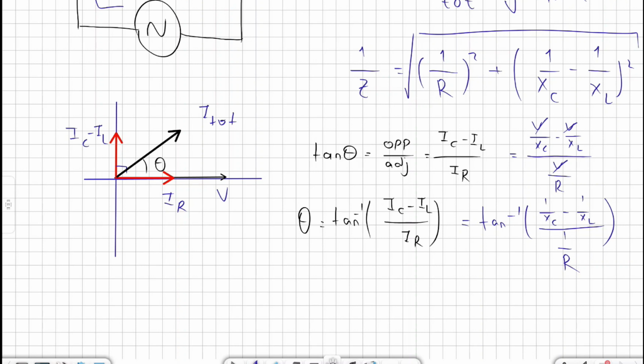We have some important points that we need to know about series and parallel combinations, and that is if XL is bigger than XC in a series combination, then VL will also be bigger than VC because they are directly proportional. As impedance or resistance increases, the potential difference also increases in series combination. Automatically, the angle will be positive because VL is in the positive side, VC is in the negative side. Positive side will be bigger, the angle will be positive.